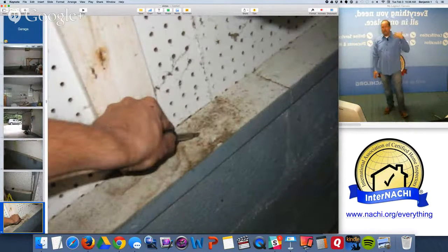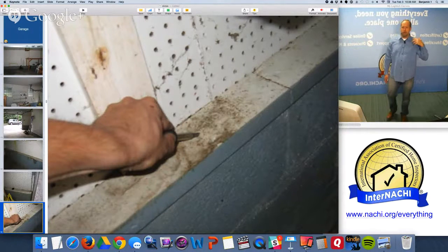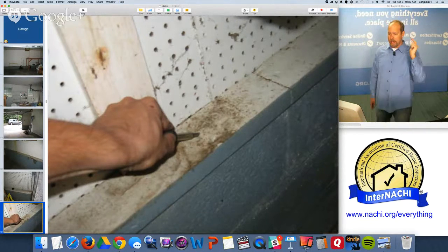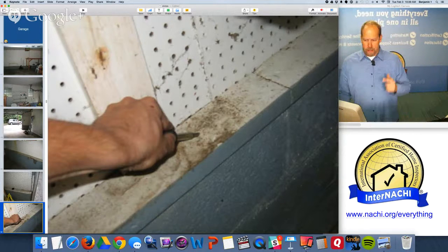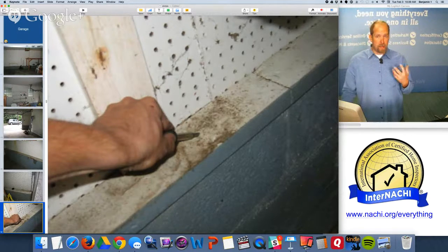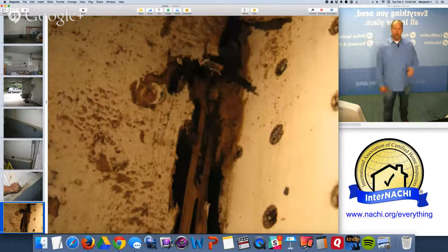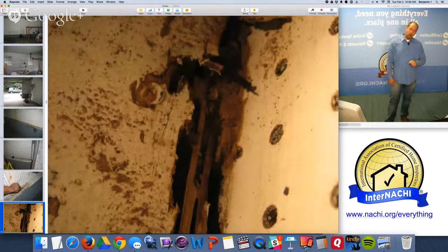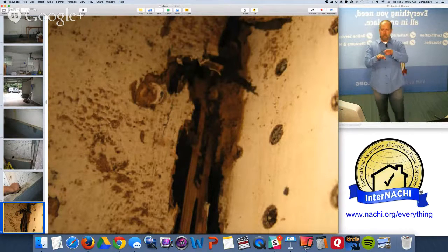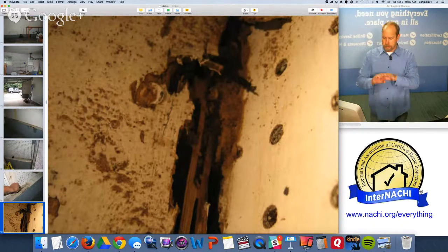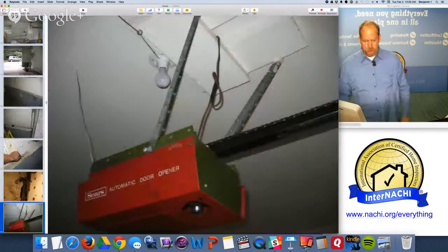So on the outside, remember we have water problems with the deck, structural problems, and also infestation. Well, I see frass or something going on, like sawdust, piles of sawdust with insect parts at this one area. And for sure, there it is. So I broke open through the wall there, where the wall and the top plate of the foundation of the garage meet, and there's infestation there and wood damage to structural components.